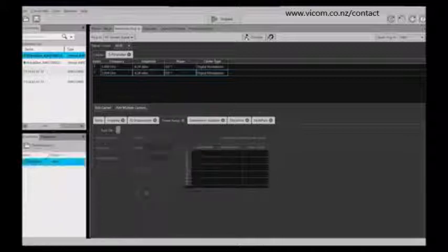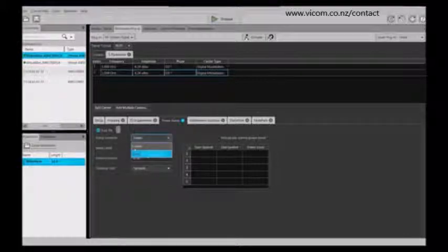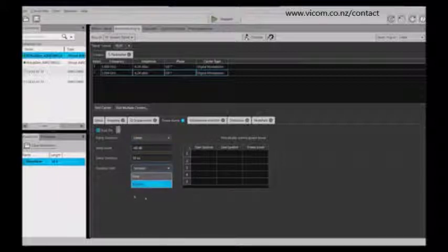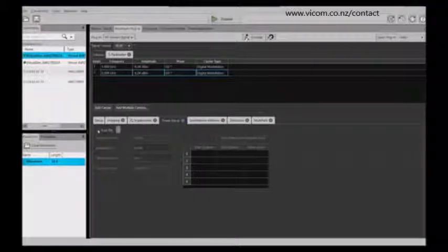So you have the flexibility of setting the criteria for your particular ramp functions. You can either be in a cosine or linear ramp function. You specify the amplitude levels, initial level, and the ramp duration, and then how many symbols, or if you want to see it in symbols or time. So this is also a very useful tool in many applications.